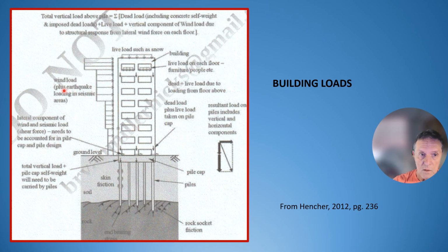You may have additional loads from wind, and you have dynamic transitory loads imposed by earthquakes. So all these loads have to be taken into consideration, as well as the soil conditions down below, so that you can design an adequate foundation, whether it's a shallow foundation or a deep foundation.